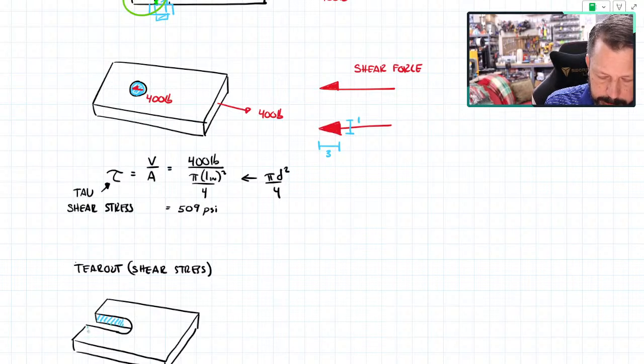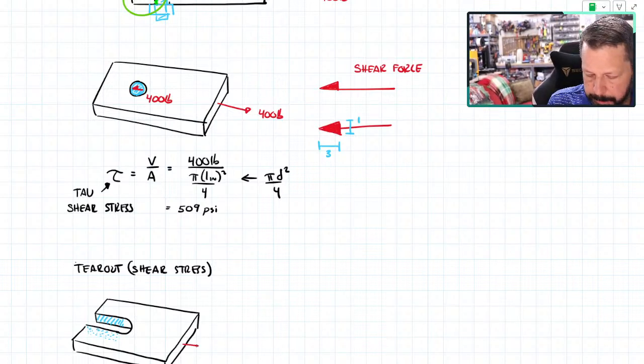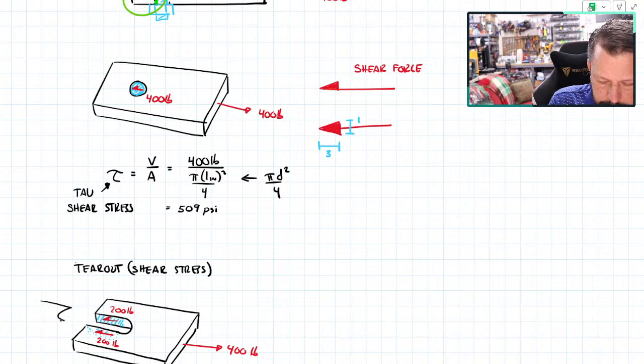So right there. And then trying to draw this one, dotted because it's on the inside that we can't see. So there's my 400-pound external load, and I've got a 200-pound shear stress here, and a matching one on this side. The little piece that came out looks like this, where this little area tore and the one back here also tore.